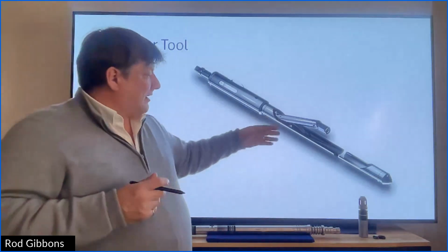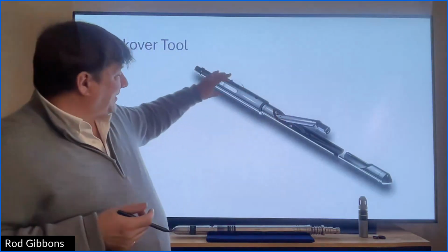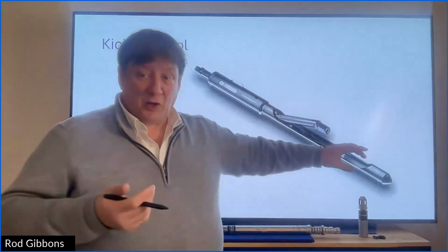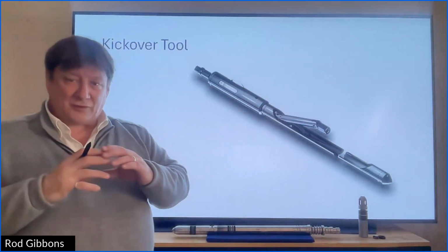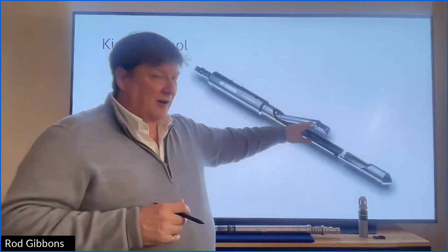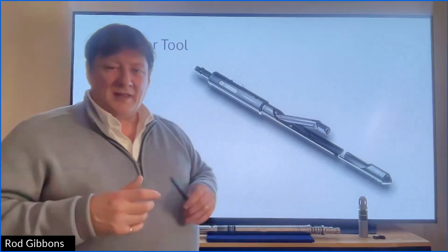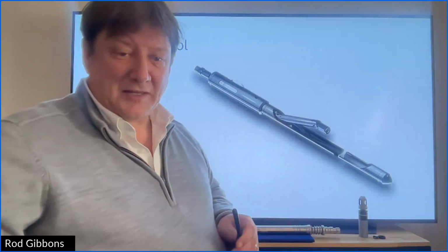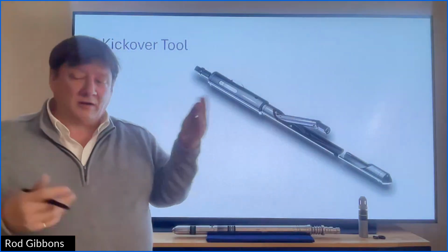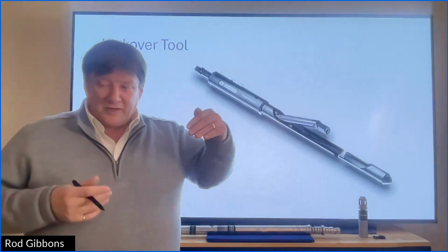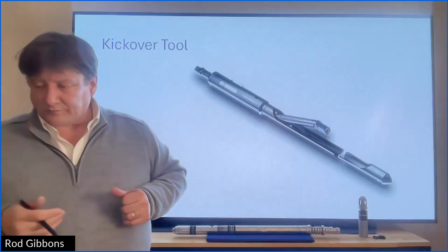And so to do that, this piece of pipe looking thing actually fits through the tubing, but there is a spring loaded arm that will come out when it has enough space to, and they call it kick over. It springs out into the side pocket mandrel to get the valve.